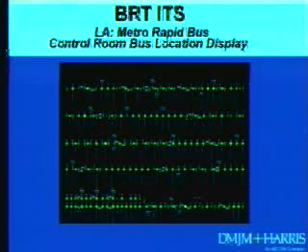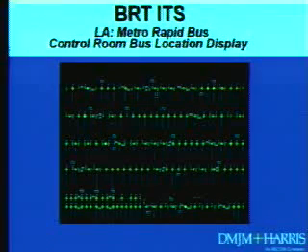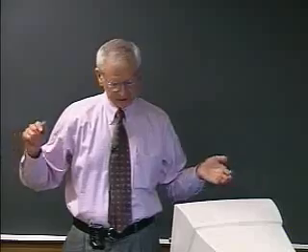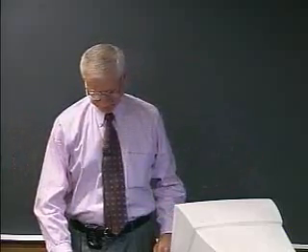And so they monitor this, and they can give the operators a little more green if they're behind schedule at the intersection. So there's signal priority if they're behind schedule, and if they're not behind schedule, you don't give them signal priority. You sort of don't want them running too fast or bunching up. So they're making a big effort. Of course, when you talk about one line, that's one thing, and the whole system is something completely different. But they're making that effort.